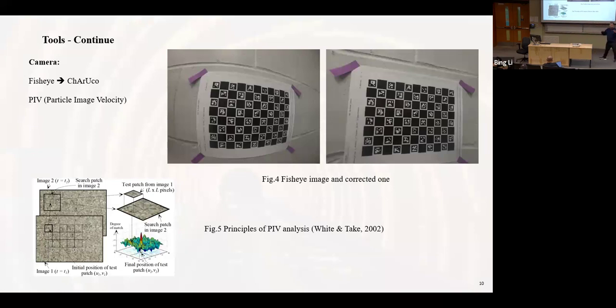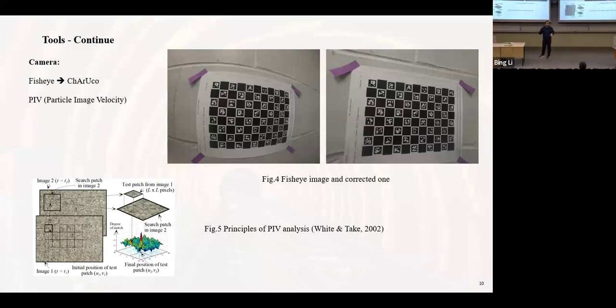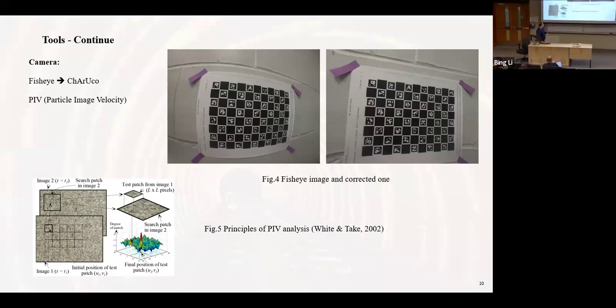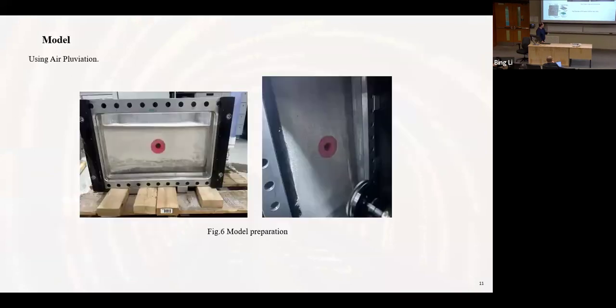Actually, what I'm doing is I record a video and convert it to a series of pictures. Then I put a mesh on the first one and put one point as a nominal point for each patch. And I track that point in the series of pictures. Using that and using a linear scale factor, I can convert the pixel dimension to a physical dimension. So using this, I can obtain the displacement or whatever I want.